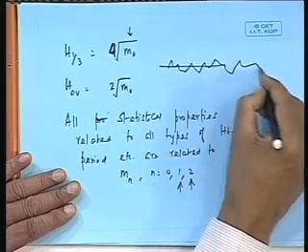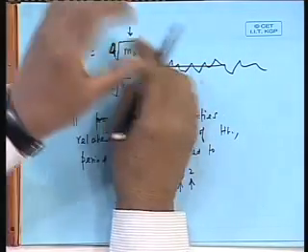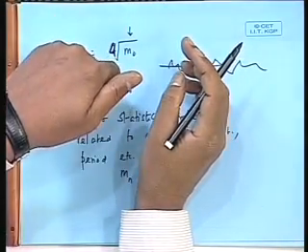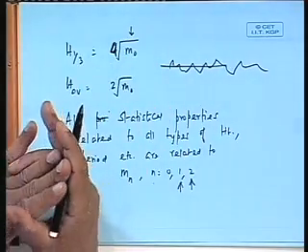Now I have to find out what is my average wave height or significant wave height. All I will do is take the area under the graph and use this formula. People don't believe it. You take this signal from where you started in the first place, take all the heights there, find out, like what we did before, the average, and you will see that they will match if the signal was a Rayleigh distribution. So this is how life becomes simple, because any time that you try to take a signal, a record at a location, obviously today and tomorrow and the day after tomorrow they will look different, but you expect their statistical properties to be the same.